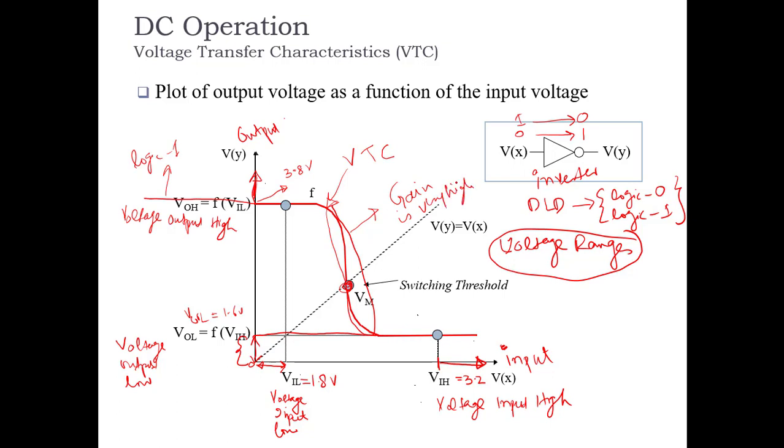So basically this is a transistor, and the transistor is an analog quantity, it's not digital. But if you use it in these regions VIL, VIH, VOL, VOH in the cutoff and saturation region, you are using it as a switch.